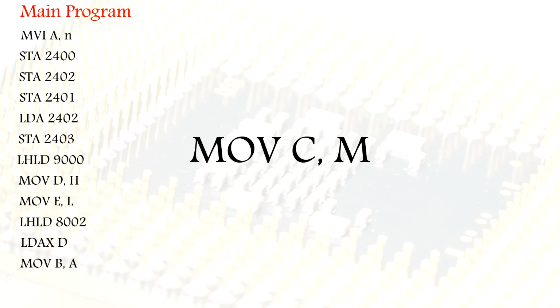And the content of M, that is the HL register pair, is pointing towards memory location 2501. The contents of that memory location are transferred to register C. So we have the element of matrix B in the B register and the element of matrix A in the C register respectively.